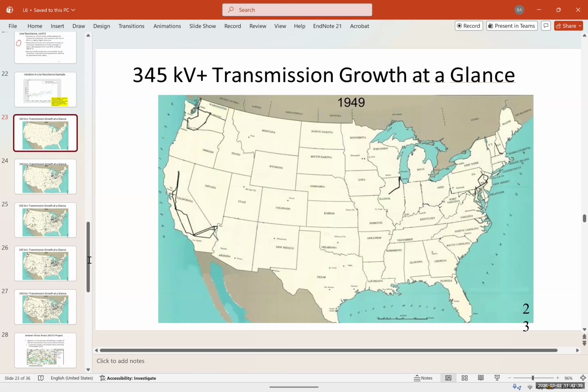When you get to a very high voltage, you need more spacing between the lines. You have to have thicker lines, and thicker lines mean the structures must be higher off the ground, and you need a bigger pole for the transmission line. It creates challenges, but it has a lot of advantages when you are transmitting over long distances.